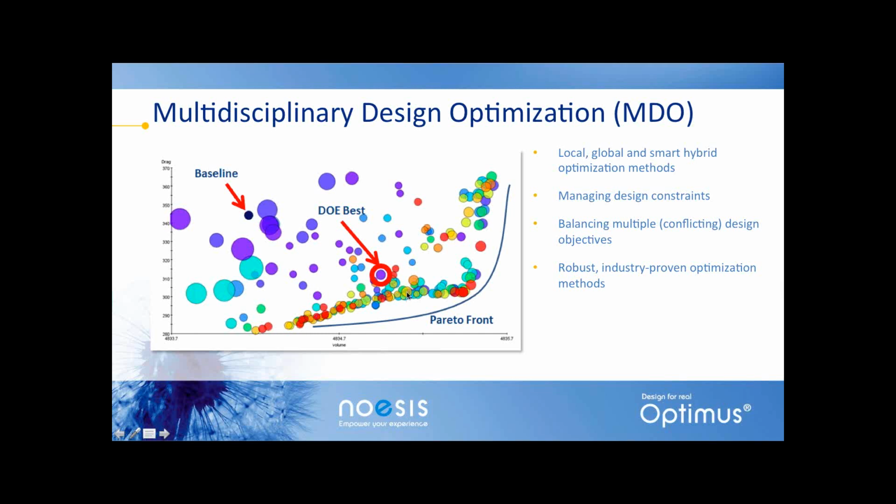And then you can go to rigorous deterministic optimization, where the software then sequentially continues to look for the best designs. Now, in a case where you have two objectives, you don't actually end up with a single best design, but rather a trade-off curve. And that's what's created at the end. It's technically referred to as the Pareto front. All of the results that fall on this front, the most outward envelope, are optimized results, but they're part of that trade-off.